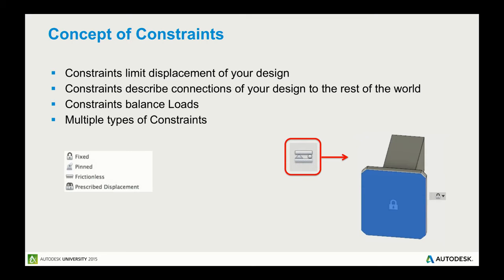Well, but you will need to make a decision when you want to stop and eliminate what you are calculating and what not, and that's what constraints are for, to define the connection between your design and the rest of the world. And by the way, it's a good practice to make that as small as possible. So in my case, I probably don't want to calculate the vibration of the floor as a part of the analysis of the lid of the computer.